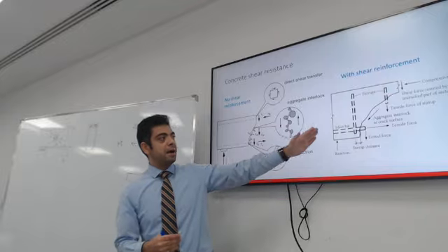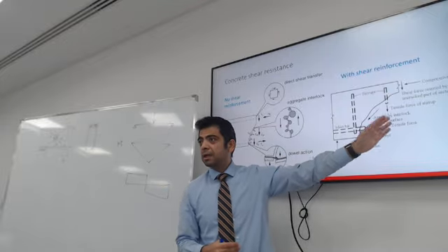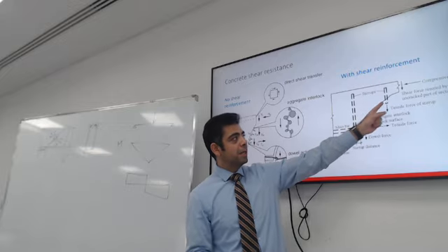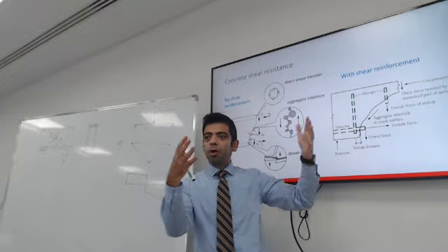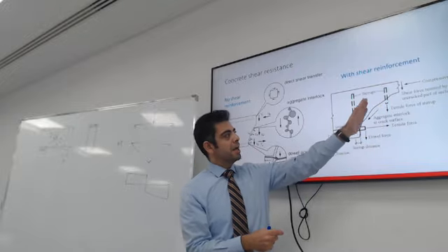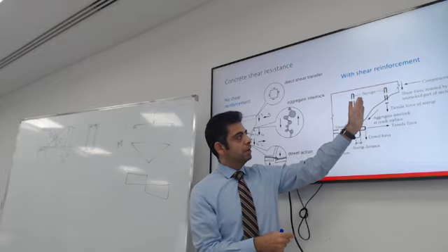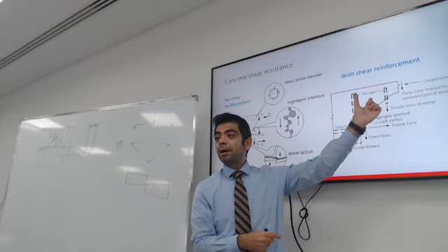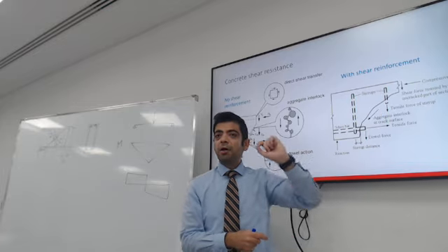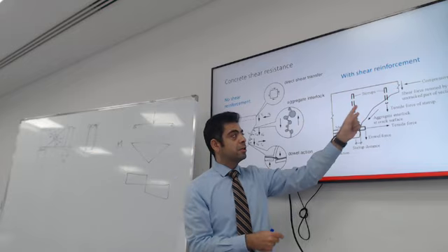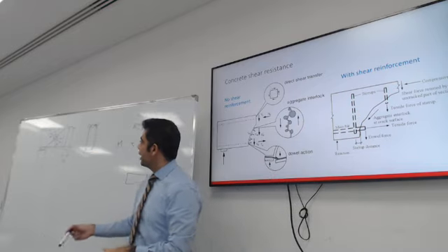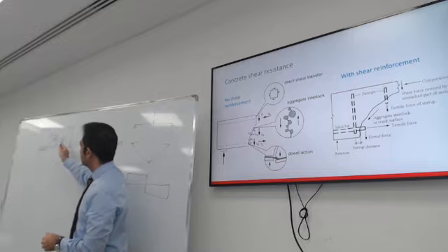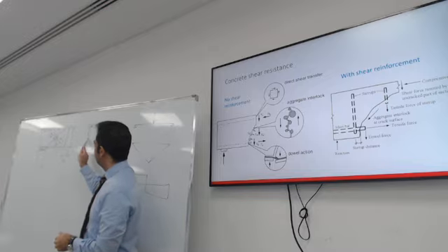What if we have some stirrups? Each stirrup is responsible for a volume or an area that is center line to the stirrup multiplied by the width. I also want to add that each stirrup has 2 branches. Do you see how each stirrup has 2 branches?